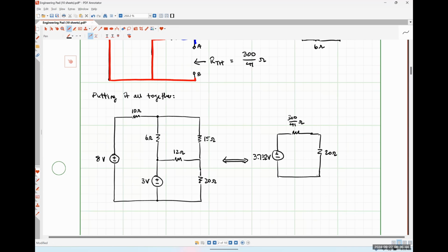That would give us an easy way to calculate our power, because I feel like analyzing this circuit is incredibly trivial. And by the way, we wouldn't mathematically determine our Thevenin equivalent circuit, we would just measure it, right? So if we have our voltage sources on and we measure the open circuit voltage, that is us measuring our Thevenin voltage. If we turn our voltage source off or whatever and measure the resistance seen looking into those terminals, that gives us our Thevenin equivalent resistance. And from that, we can just construct this circuit to do a very simple power analysis and find out, hey, am I going to burn this thing out or not? So very, very useful tool used in industry all the time, particularly in troubleshooting and things like that.